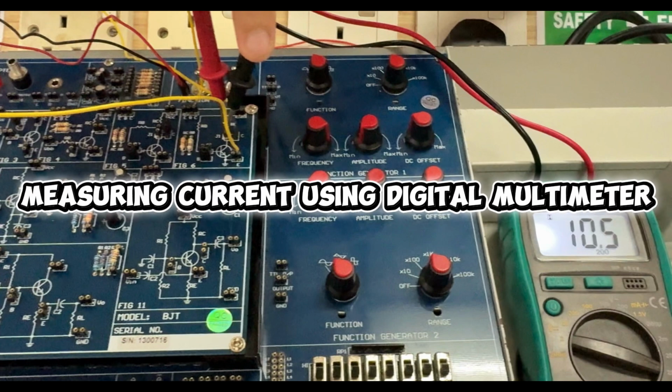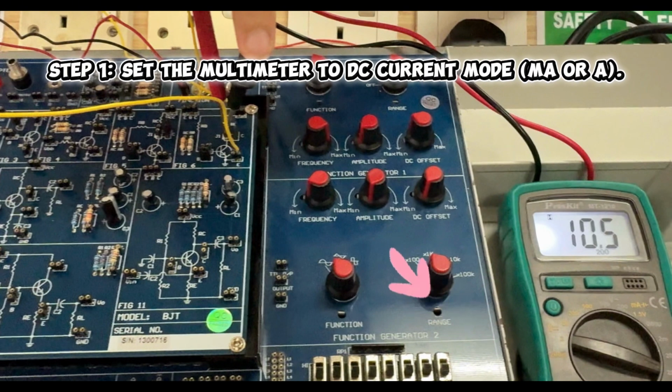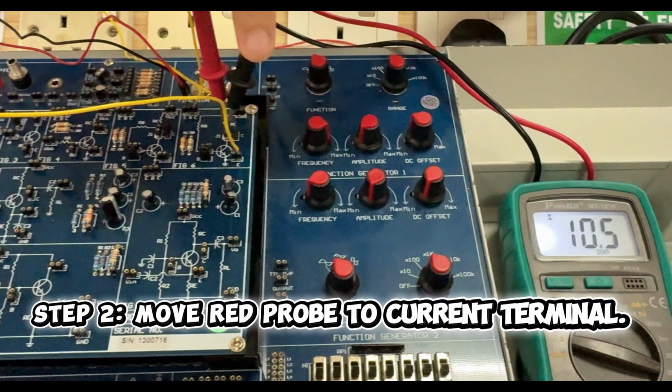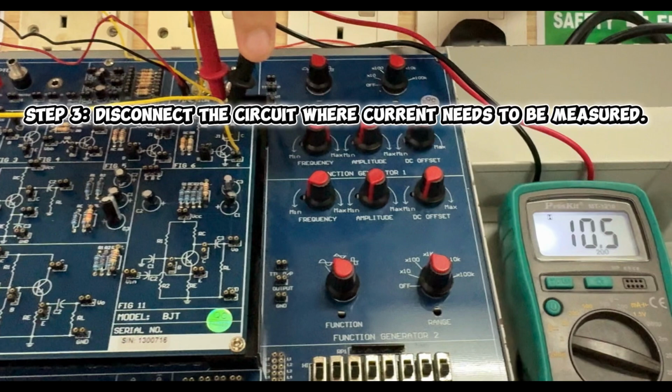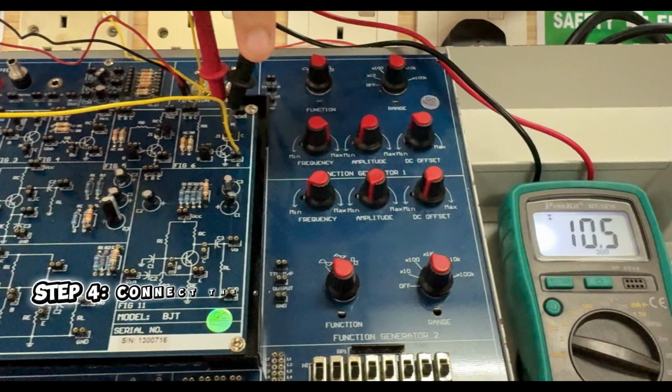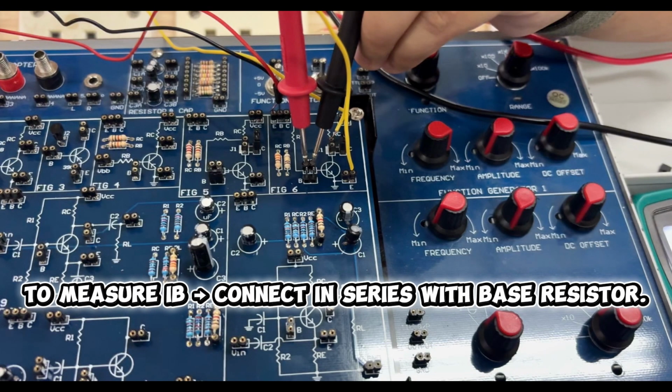Next, we need to measure the current using a digital multimeter. The first step is to set the multimeter to DC current mode, milliampere or ampere. First, we need to move the red probe to the current terminal and disconnect the circuit where current needs to be measured. Then we connect the multimeter in series with the circuit. So to measure the IB, we need to connect in series with the base resistor, as shown in the video.